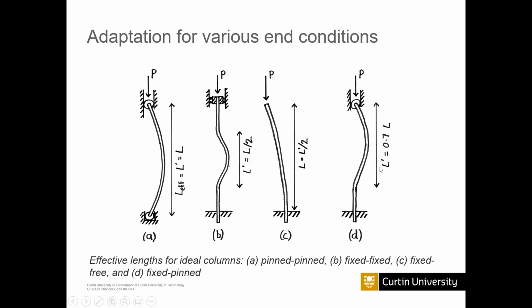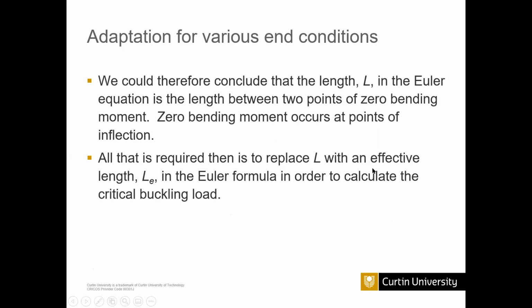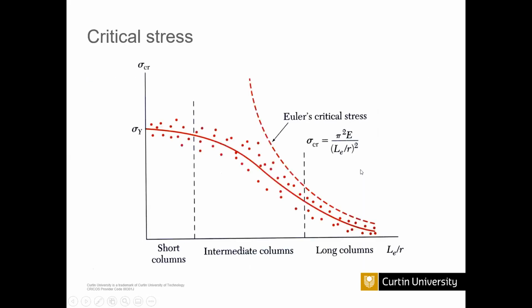Okay, because that is the thing you learn. So I hope you understand now what is the meaning of effective length. So in these equations, we are not going to substitute the complete column length. If it is pin end, we can use LE equals the complete column length. But if it is different end conditions, you need to consider effective length.